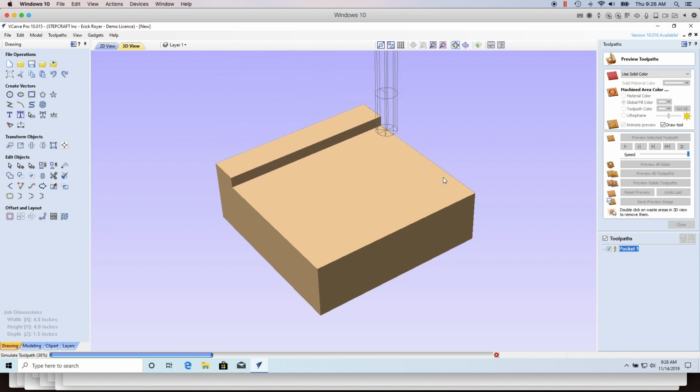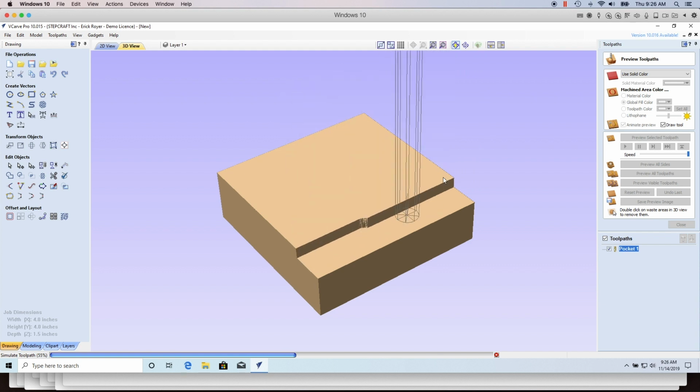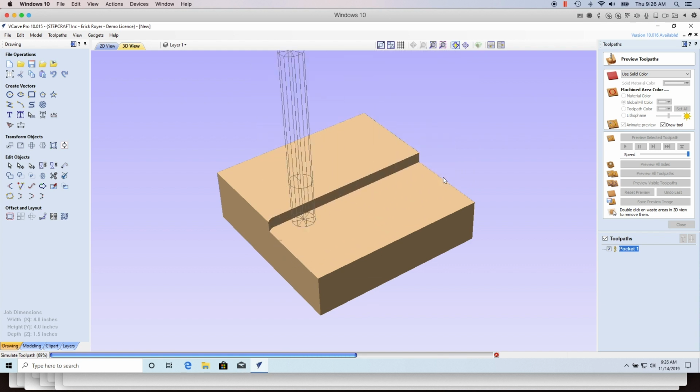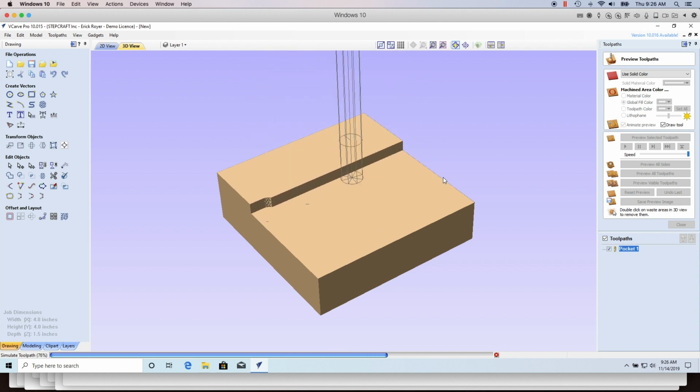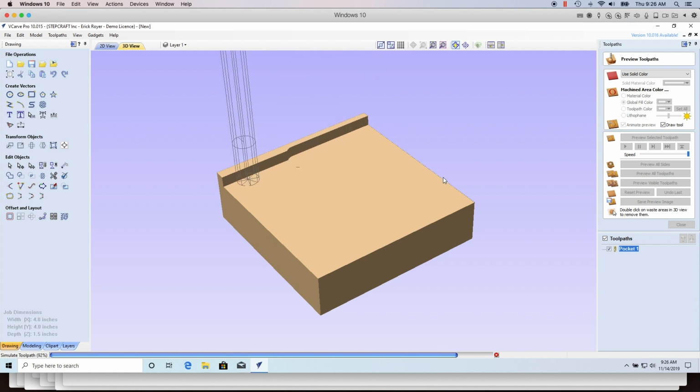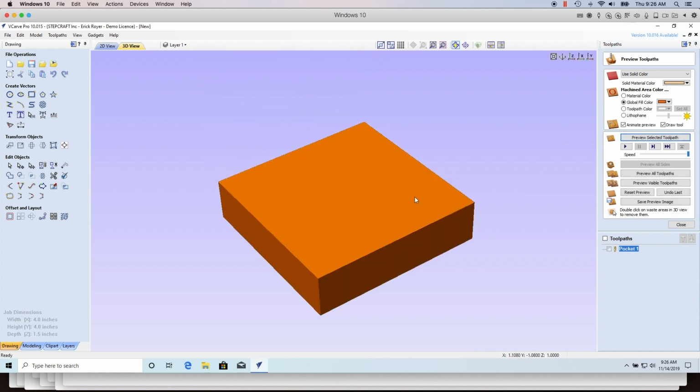And then we're going to come back as soon as that's done, and we're going to go ahead and take the second 1/4 of an inch off on this layer. And again, this is keeping a constant load on that cutter and on your machine by doing it this way. You don't have to worry about the variances on the top of the material. So you can see here, if you look down here, my final cut height now is 1 inch.